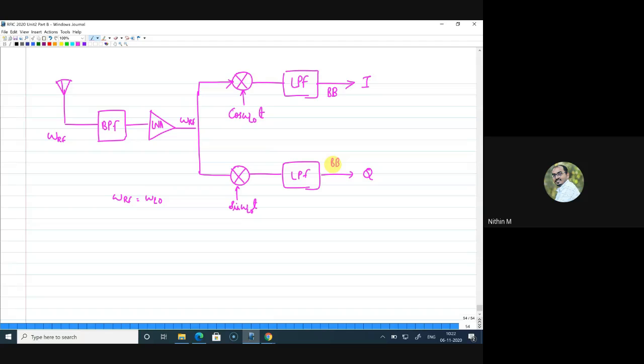Yes, that is an issue in that sense, but there are methods to track and generate the same frequency. Whatever you have commented, a phase locked loop, will actually help in this. Whenever we draw an oscillator, especially in a receiver, the oscillator is sitting inside a loop where there is some feedback mechanism involved, and we call that a phase locked loop, right?